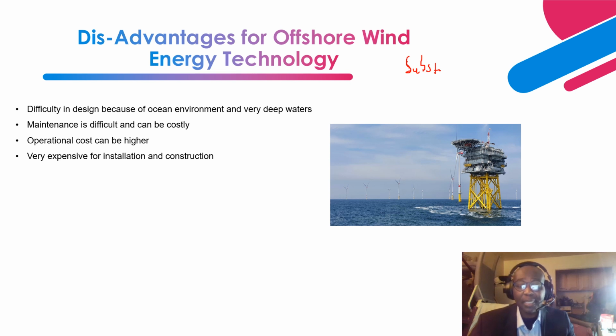But this substation is elevated, right? With these supports. The whole substation elements, switchgears, converter transformers, and converters are all located here. Cabling, right? They are all located here. You see that in between all these wind turbines, there's something they call the cabling, which is called inter-array cables, right? You can have a radial, then star arrangement.